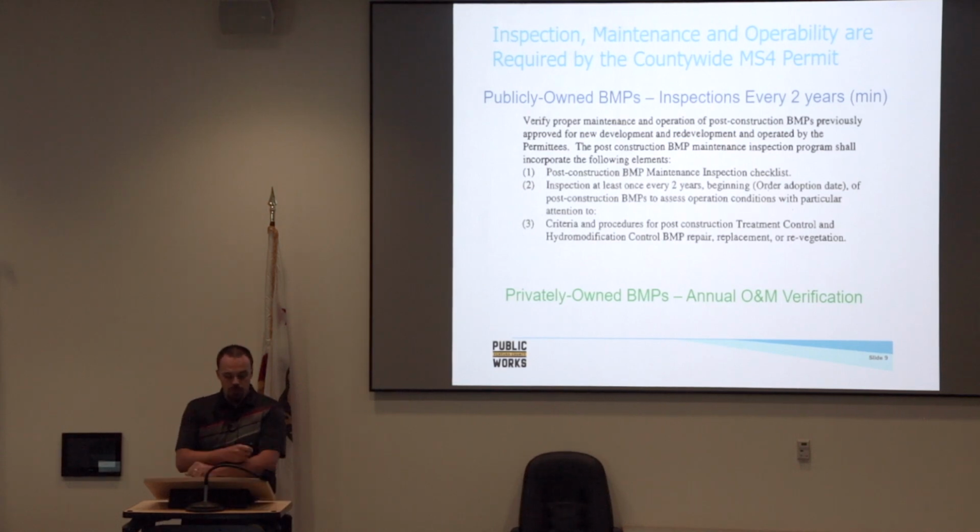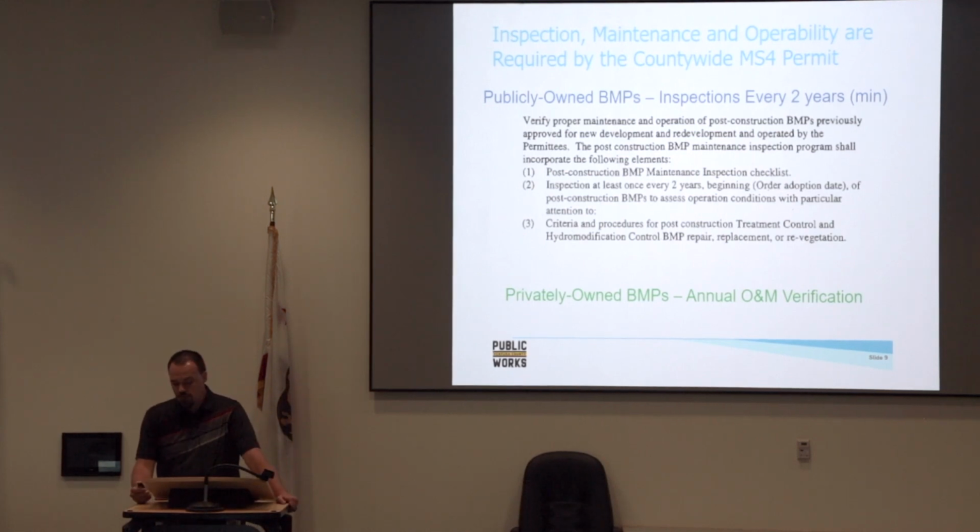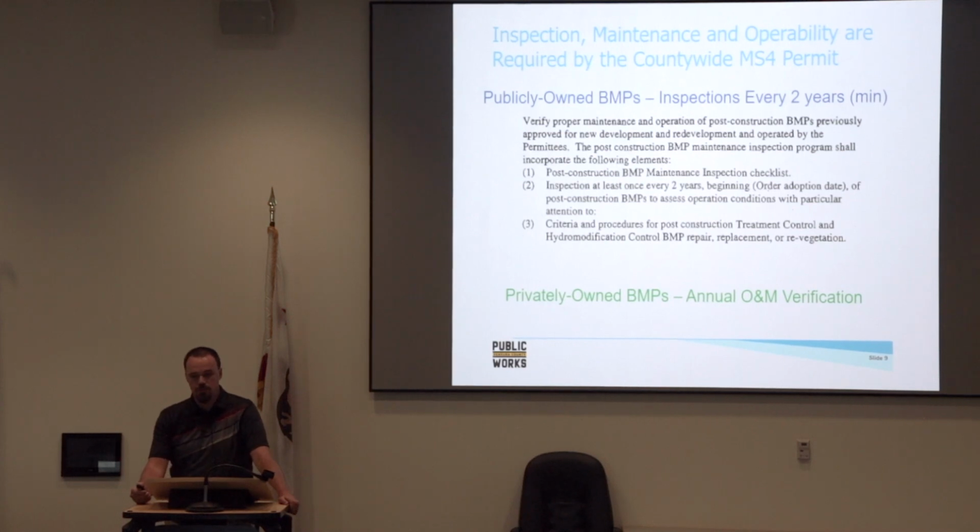Inspection, maintenance, and operability. So I just wanted to touch on these. In the MS4 permit, it requires all publicly owned BMPs to be inspected at least twice a year, and privately owned BMPs have annual verification requirements. So we do our own internal inspections of our post-construction BMPs.